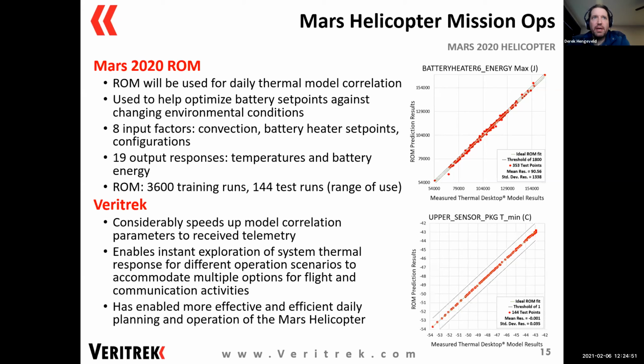The ROM that we built had 8 input factors. Across the board, it consisted of convection conditions, battery heater set points, and different configurations. We're also tracking 19 output responses. We used 3,600 training runs and 144 test runs to really vet this thing.